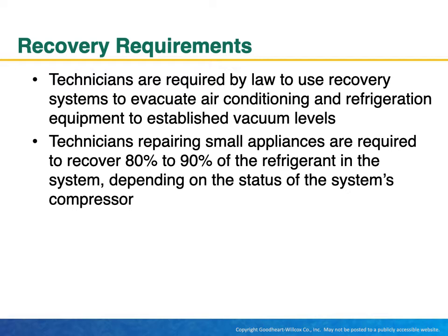Technicians are required by law to use recovery systems to evacuate air conditioning and refrigeration equipment to established vacuum levels. Technicians repairing small appliances are required to recover 80% to 90% of the refrigerant in the system, depending on the status of the system's compressor.